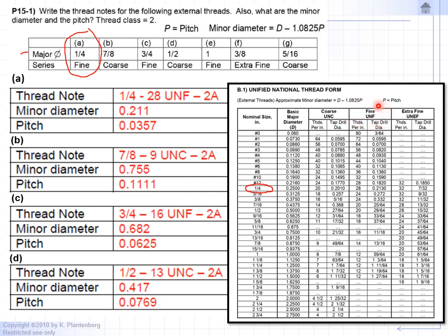In that case, the bolt is going to feel a lot of stress, so you're better off using more threads than less, like coarse. Coarse thread you tend to use on non-moving parts or bolts that don't go through as much stress.